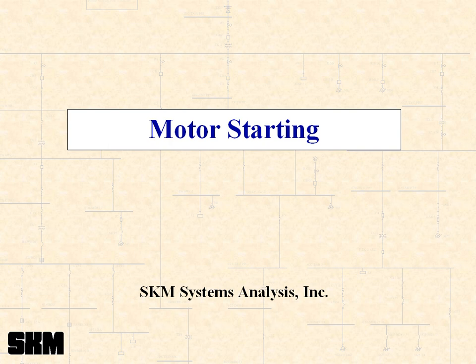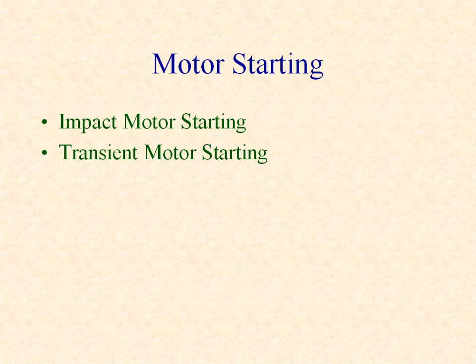The topic of this tutorial is motor starting. The two most common motor starting simulation methods are impact motor starting, which is a single snapshot when the motor first starts, and transient motor starting, which is a time-based simulation of motor acceleration.